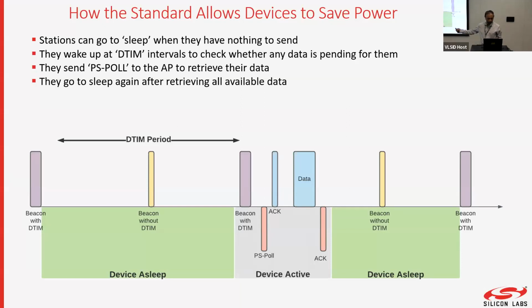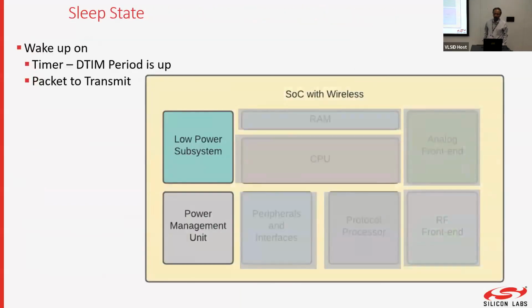But the standard allows you to sleep. And if you are asleep, how do you implement it? As an SoC designer, how do you implement a sleep state? Well, that's where you have to make sure that your power management unit turns off power to everything. Now, the RAM may be on or off. I'll talk about it in a minute.